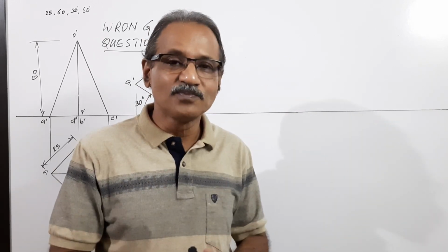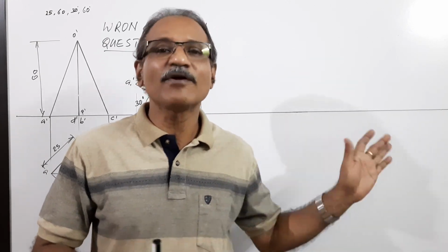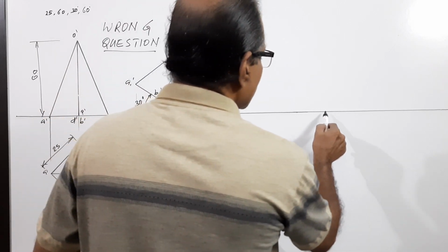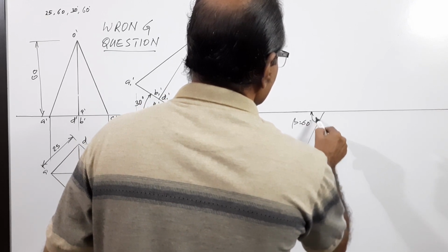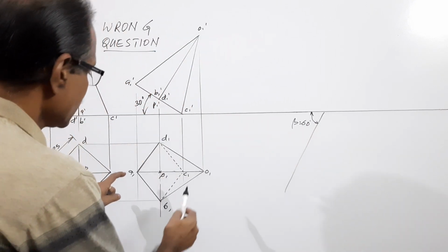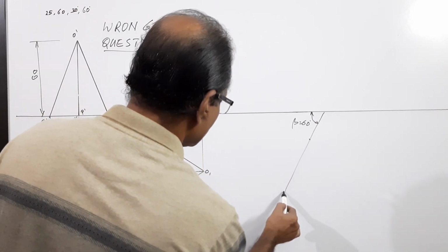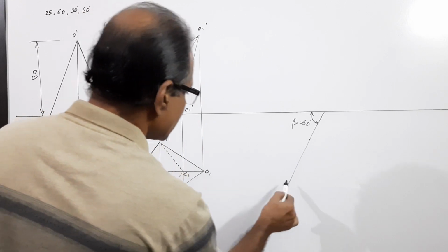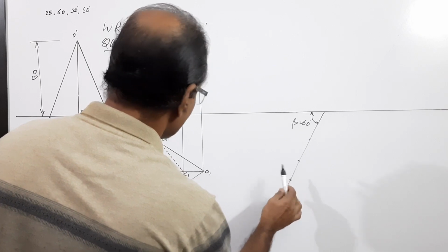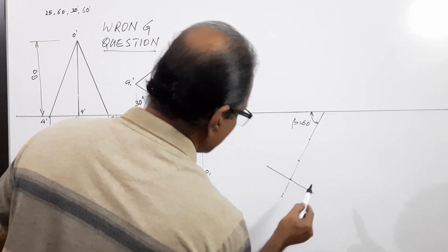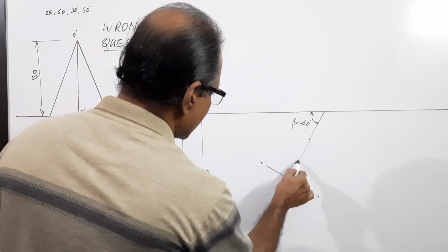Now let us assume beta is 60. Let's correct the question ourselves and make beta equal 60. Agreed? Now we are going to draw it. Take any point on the xy line. Draw a line. Beta equals 60. Now take this length and mark. Take this length, mark. Take this length, that's same. Mark. Draw a perpendicular here. Mark. Mark. Connect.